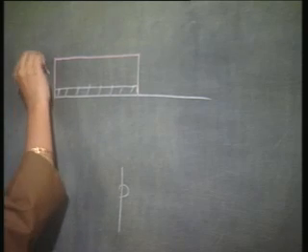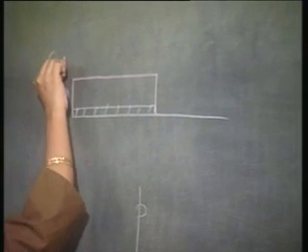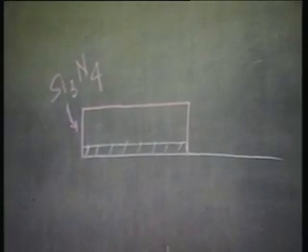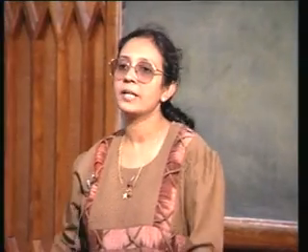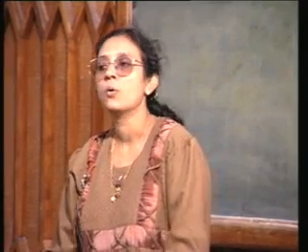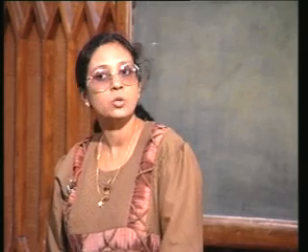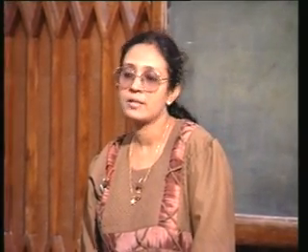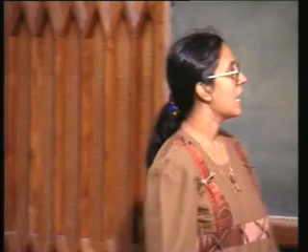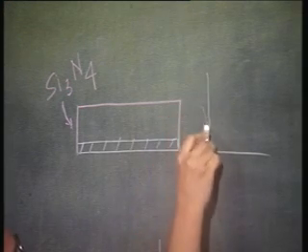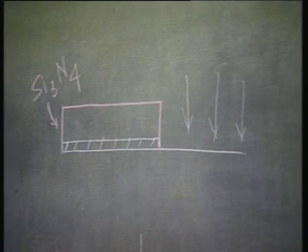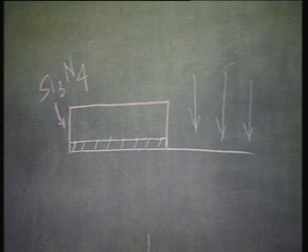This is nitride sitting on top of the pad oxide. You can have finer techniques here like sidewall masking and all that, let us not bother about that. Essentially, you are planning to carry out a low cost technique. You are going to protect a certain region with an oxide nitride mask, and the rest of the region you are going to have a phosphorus implant.